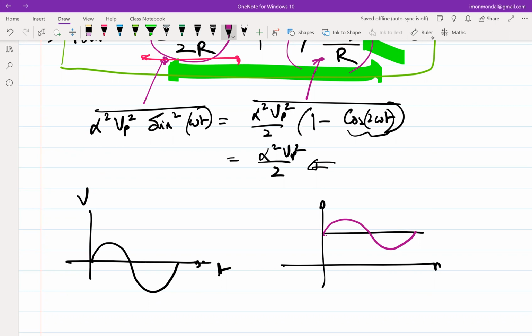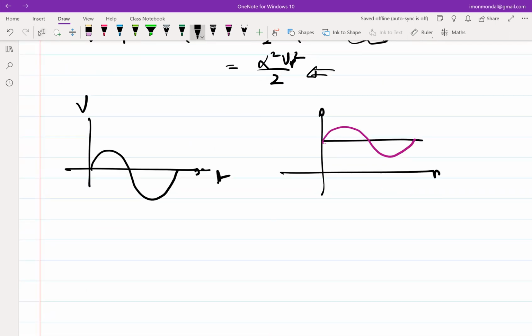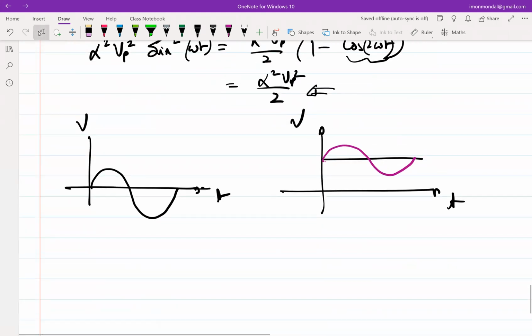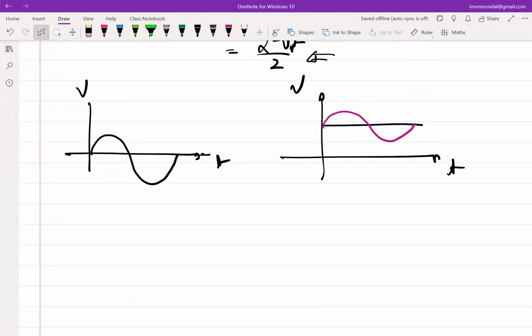Right? So now if I look at the signal, you will get the total. This is the total, right? So this graph, V versus T. Have you used a spectrum analyzer ever? No. Okay. So what I am trying to get at here is that if you do a Fourier transform or a Fourier analysis of this, you will get frequency components. What frequency components will you get? You will get them at 0 and omega naught.